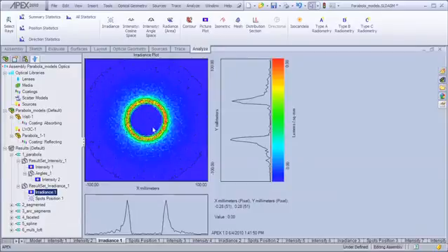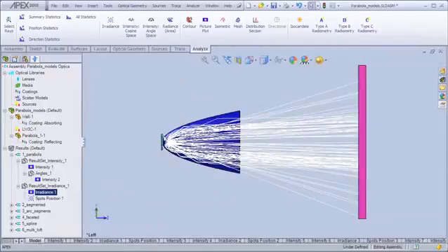And the reason we don't see anything in the center here except the rays that are coming directly from the LED is that no light can hit the base part of this reflector way down here towards the center part because the LED is blocking it. And there's also the hole in the reflector. So that prevents us getting any energy in the center of our illumination pattern. This is the primary problem with parabolic reflectors.